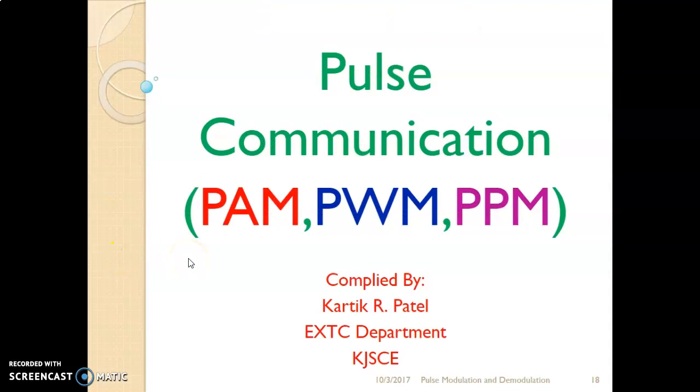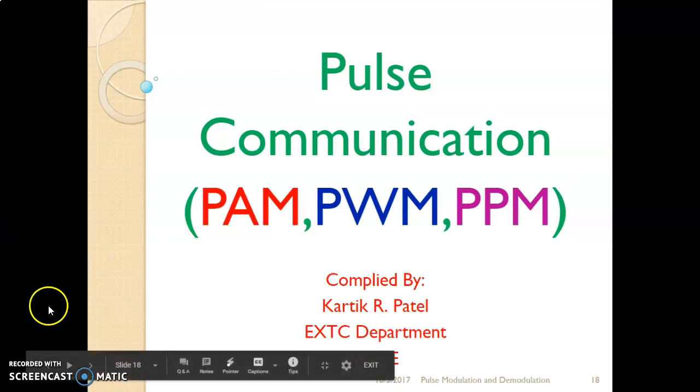So in PWM we are changing width of the pulse signal in accordance with instantaneous amplitude of modulating signal, and because of that we get variable duty cycle waveforms at the output, which can be used in industrial application for controlling amount of power which is transferred to the load.